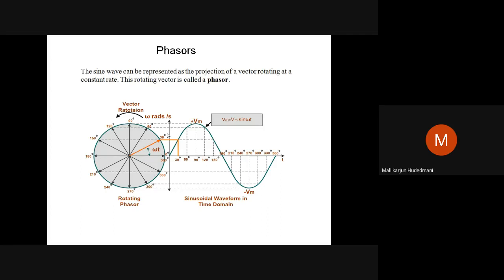Then how is it represented? Yes, look at the representation. Let us consider a sinusoidally progressing wave as Vm sin omega t, where omega is called the angular velocity of the wave which is progressing, having its peak value Vm and minus Vm respectively. Now, how is it possible to represent this? To represent an alternating quantity by a rotating vector, we require three parameters.